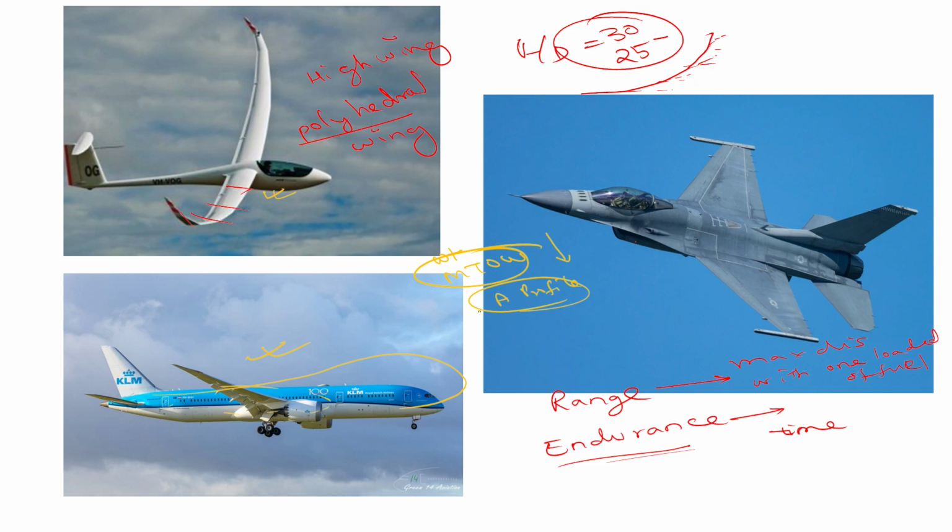And if you ask how this aerodynamic profile creates benefits, or how it creates pros and cons, there are a lot of things. First and foremost, I will say the parasite drag. Based on the length of the fuselage, we can decide what the parasite drag will be, or mathematically we can express that as the CD naught parameter. So that's why we have to constrain different types of fuselage for different types of aircraft.